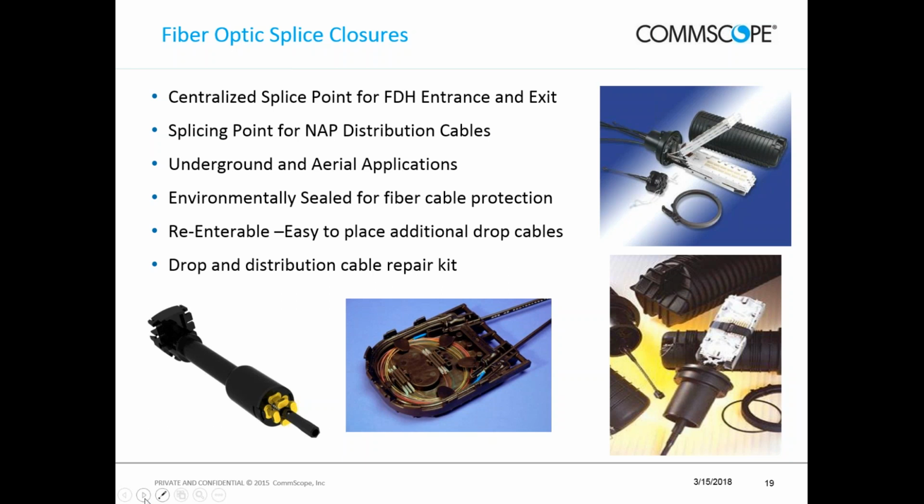The splice closure always needs to be able to be mounted in an underground or an aerial application. Obviously, the most important thing is for it to seal against outside influences in the outside environment. So it has to have a really good seal on it, so it's not going to leak water or allow any type of contamination into the device. Another thing that makes it really user-friendly is if you choose a product that allows you to re-enter that splice closure easily, without cutting off the shrink boot and Bishop's tape and all of that stuff.